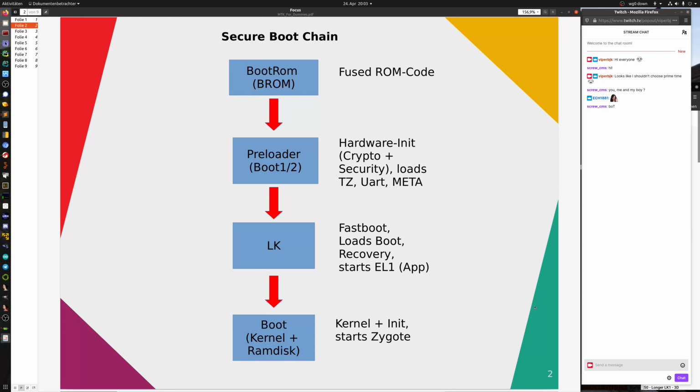It's being stored in boot 1 or boot 2. Most of the time, it's just in boot 1, and other times you've got a shadow copy in boot 1 as well, and boot 2 normally contains the serial numbers for the Wi-Fi and for the device itself.